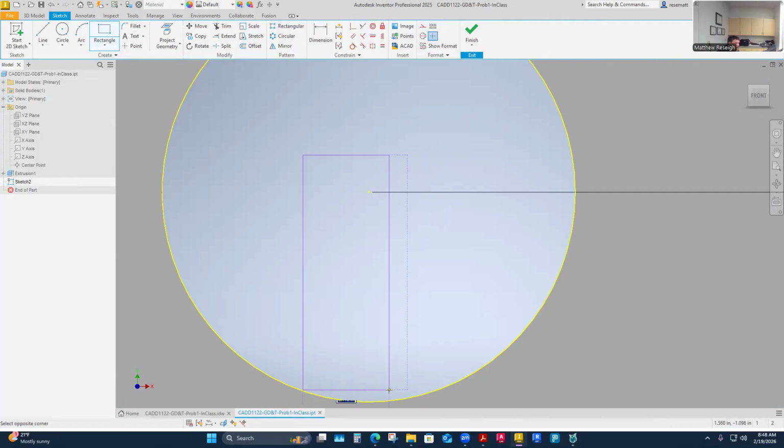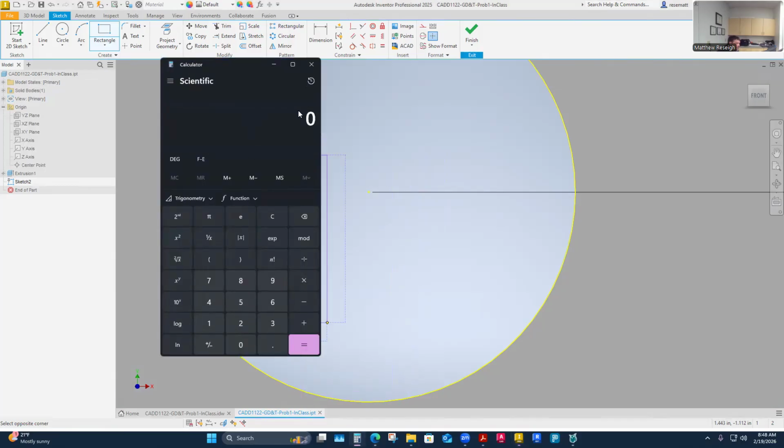So really that tells me the part could be, and I'm just thinking of my dimension, it's 0.563, and it can be this big. It could be minus 0.005. So the dimension would be acceptable if it was 0.558, because that is minus 5 thousandths from the dimension I'm given on my drawing, using the tolerance implied by my tolerance block. It could also be 0.563 plus 0.005. So it could be as big as 0.568, or it could be located at that dimension and be within what I call the general tolerance block on the drawing's specs.